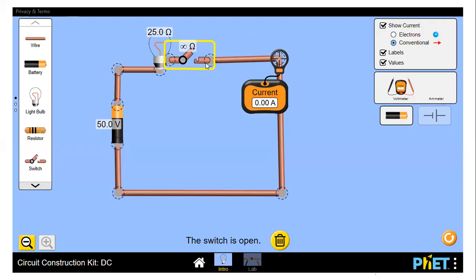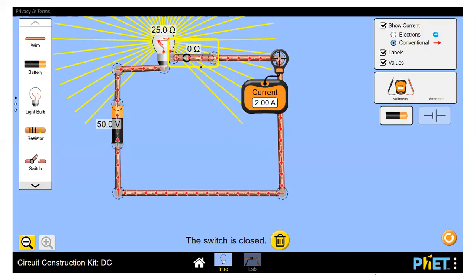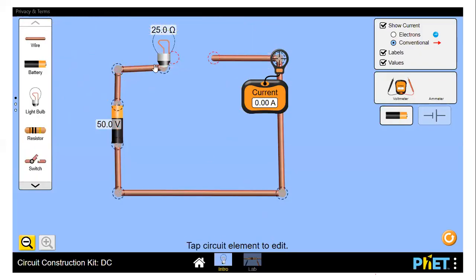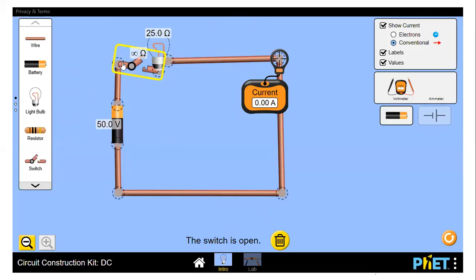And that's why please remember that this switch has to be always not at this point, it has to be at this point. So I'll reconnect the circuit. It is a simple, small fact which we need to understand. Now it's perfectly all right. When you turn off the switch, you can replace the lamp. You won't receive a shock because this is infinite resistance.